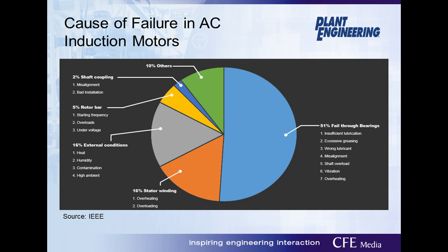When a motor is matched to an application, it's typically matched based on nameplate horsepower and running speed. In many applications, a motor may experience short-term overloads, and due to this, most motors will be marked with a service factor. The service factor can be found on the motor nameplate or in the product literature. Most motors are equipped with a service factor greater than 1.0, which means they can safely operate above rated load. However, always verify nameplate service factor if you suspect overload is occurring. And I think Ronnie will expand on that more later on.